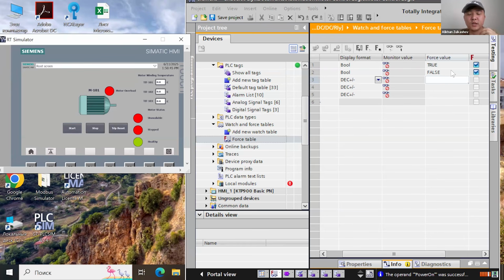It can be auto, it can be manual, but it is probably better to have it in manual mode because it gives the technician or field engineer an opportunity to check. Then when he makes sure that everything is okay, he will just press the reset on the overload relay.